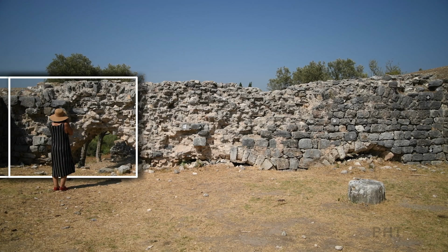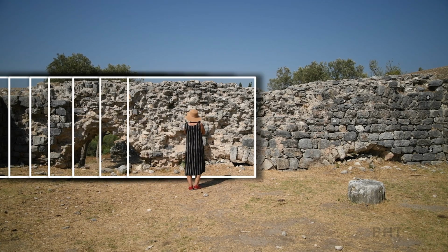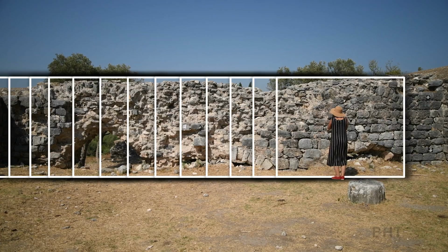For the next image, move a good step further again. Now we have an area that is already covered by 3 images. Object points within this zone can therefore already be modeled by the intersection of 3 image rays. We continue in this way until we reach the end of the object or one side of the object.